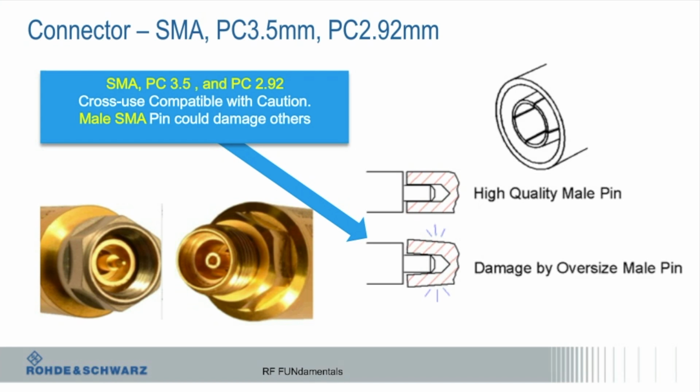And this obviously isn't as repeatable. When you see it's kind of bent like that, you're going to see every time you connect it, this isn't going to look the same, right? This may be touching down here instead of here, or it may rotate. So if you looked at the VSWR or whatever, it's going to look different every time you reconnect it. So that's why you care.